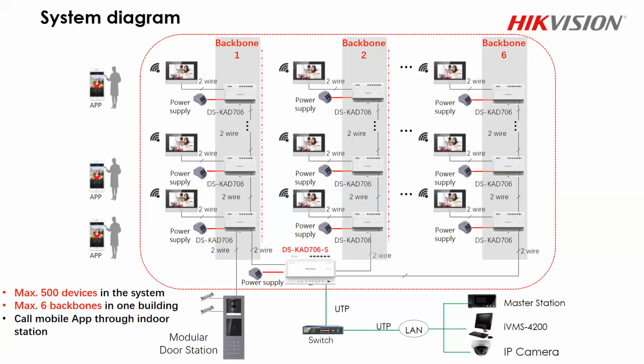For the secure module, it's connected via the RS-485. In our release notes, we have explained how to connect to that. The secure module will be needed to connect to the door stations via the RS-485. The release note is available on our UK portal, where you are able to download all our latest firmware, and it's also included in there.